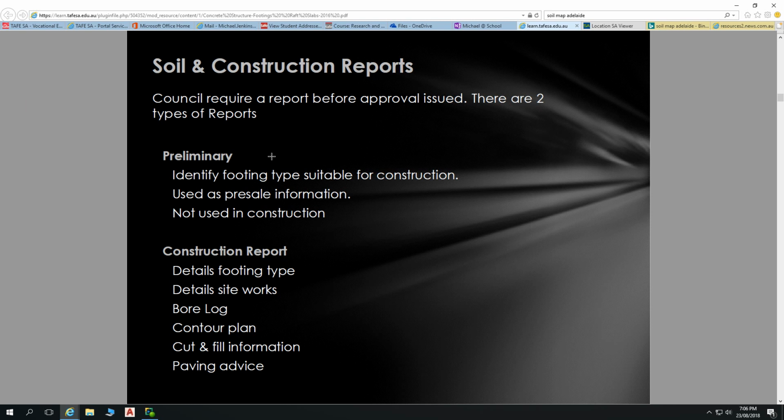Yeah. I think it's more about stopping moisture getting to your footings, because in a reactive site, what you don't want is a lot of moisture right next to the building. In fact, what you don't want is moisture changes. You don't want it to be saturated, dry, saturated, dry. You want that moisture to be stable.